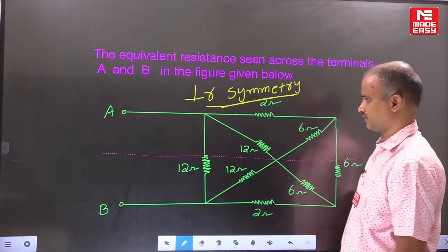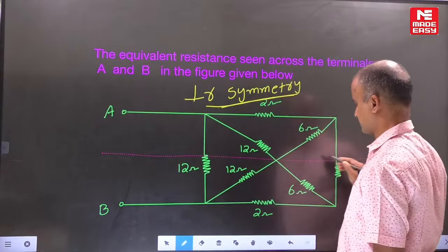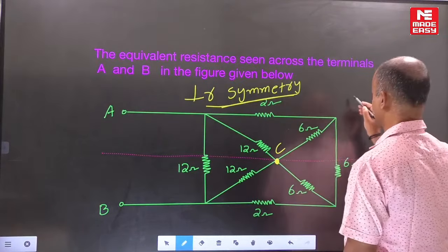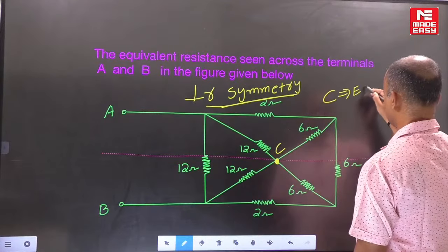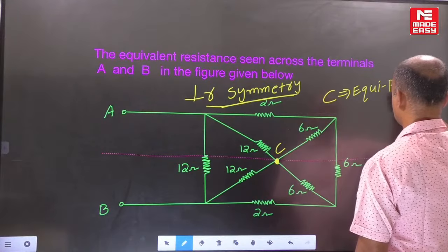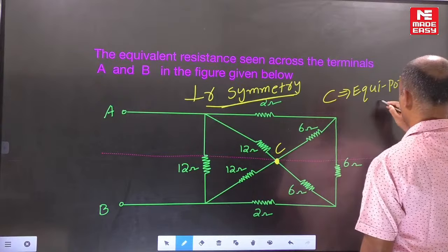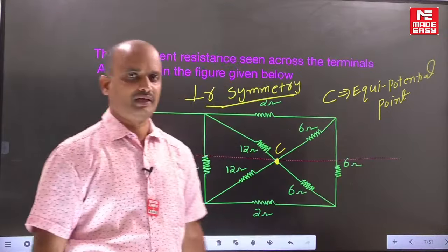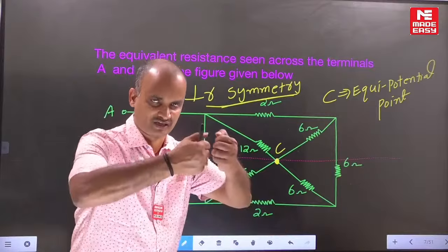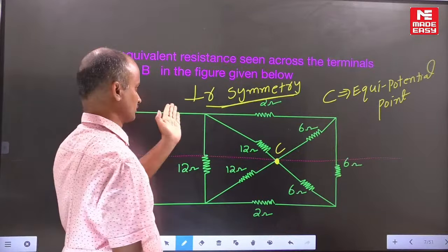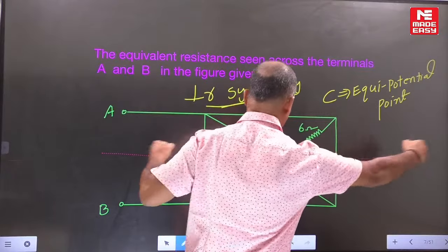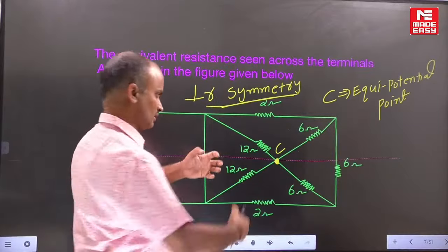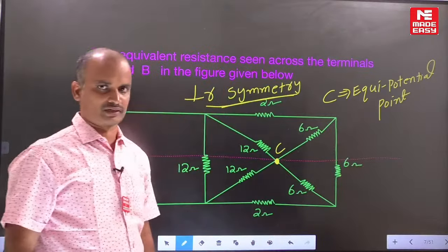Okay. Now according to this perpendicular symmetry, whenever the dotted line is indicated, if any joints are present, the corresponding point is named the equipotential point. Now in this example, according to perpendicular symmetry, this equipotential point can be disconnected along the dotted line. Since the dotted line is indicated along the x-axis, it should be disconnected along the dotted line.